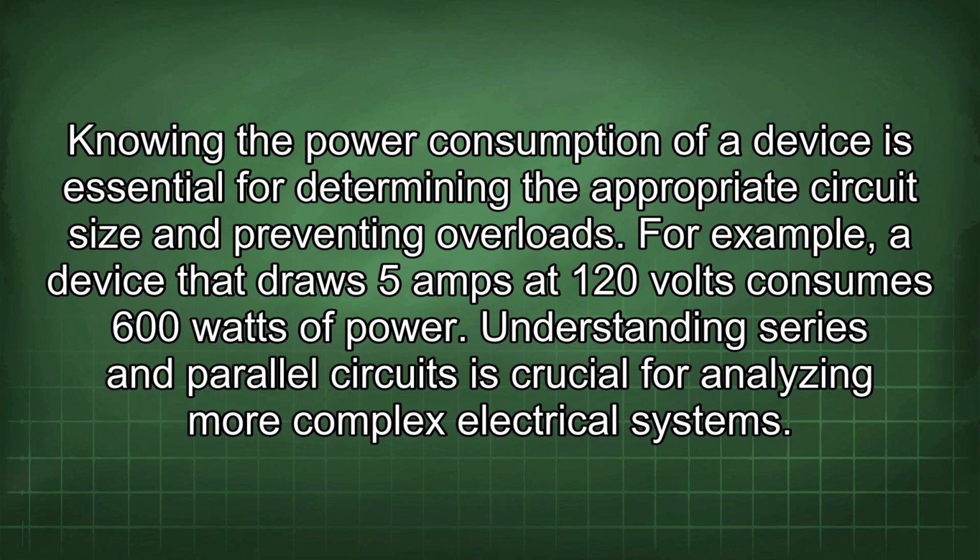Knowing the power consumption of a device is essential for determining the appropriate circuit size and preventing overloads. For example, a device that draws 5 amps at 120 volts consumes 600 watts of power.